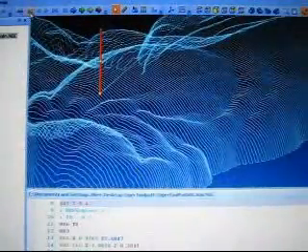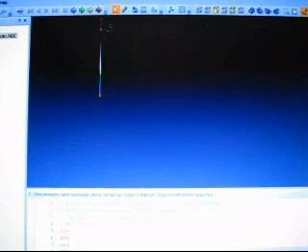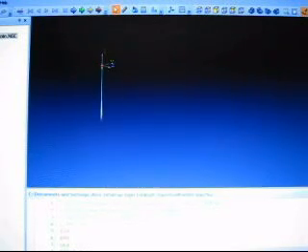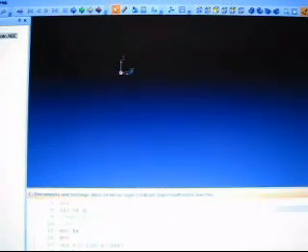We'll go to that line. It's one of the first lines in this code, right there. That's going to a Z -4. So I just want to set that to a Z.1, so it jumps up to my clearance, and we'll change it to a rapid motion from a G01 to a G00.